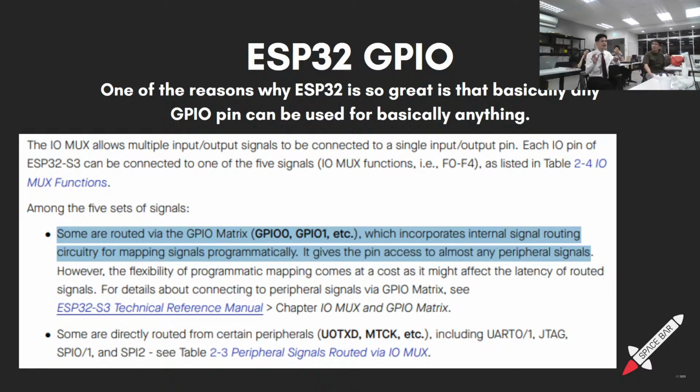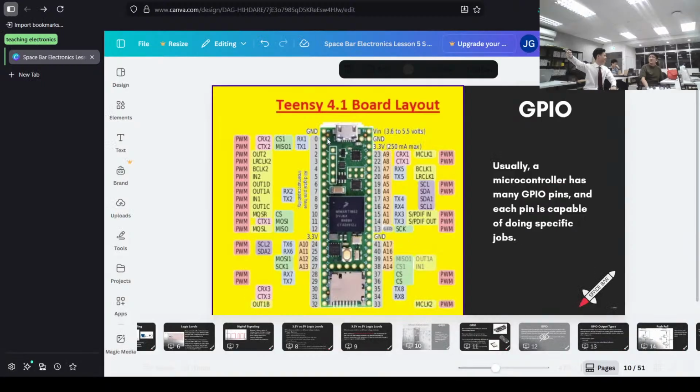This is an Arduino, but it runs at 600 megahertz. It's like a strong Arduino, and it's got a lot of pins. These are the pin numbers here. Then these have A0 to A9. These can do analog, so this can do analog to digital. Then there's a bunch of other functions. PWM just means it can turn on and off really fast. He'll go over that later. The rest of these are basically communications, which we'll also go over later.